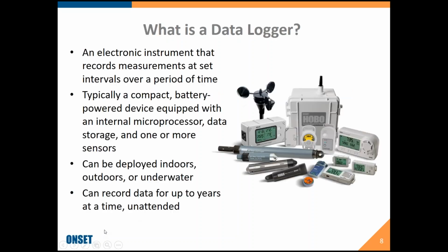All right, let's get started then. Right off the bat, what is a data logger? Well, a data logger is an electronic instrument that records data either over intervals or over a period of time. Typically, it's a compact device with a battery and a microprocessor, has some flash data storage, hopefully, and one or more sensors. They use loggers indoors, outdoors, and underwater, and they usually can record for up to years at a time unattended.